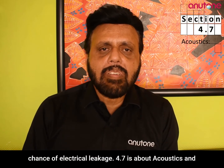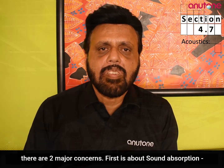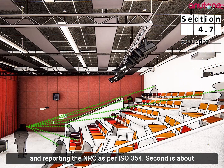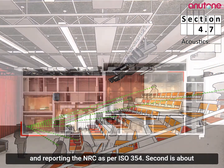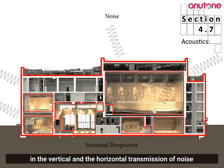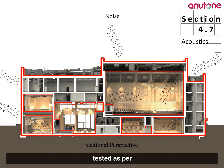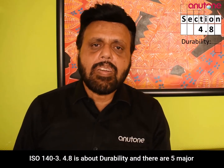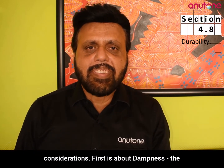4.7 is about acoustics, and there are 2 major concerns. First is about sound absorption and reporting the NRC as per ISO 354. Second is about sound insulation or noise isolation, as we call it: reduction in the vertical and the horizontal transmission of noise, tested as per ISO 140 part 3. 4.8 is about durability, and there are 5 major considerations.